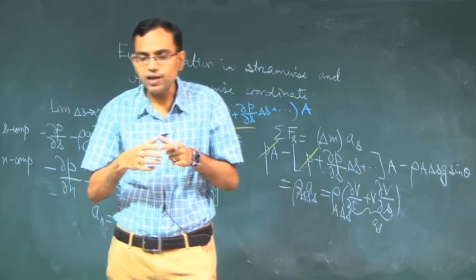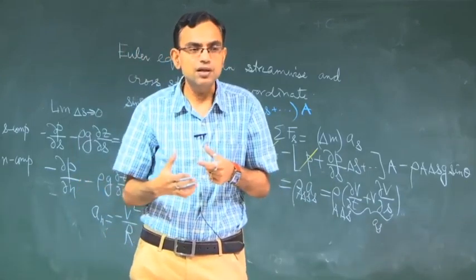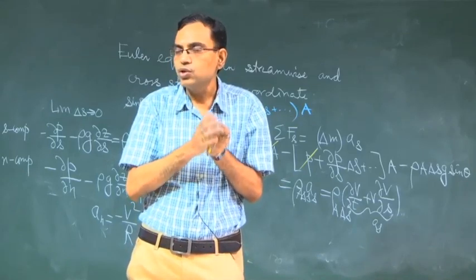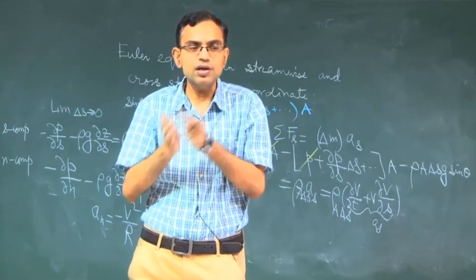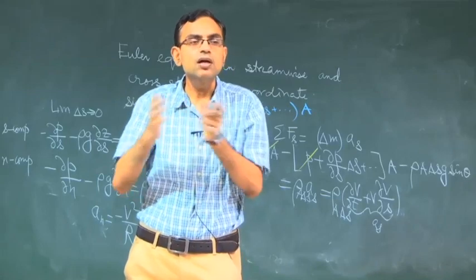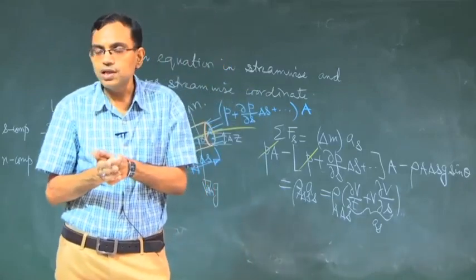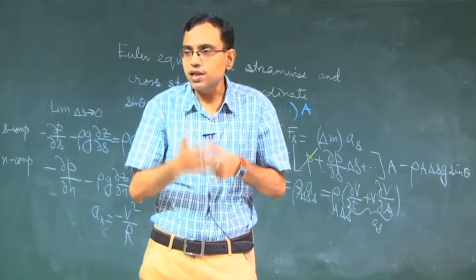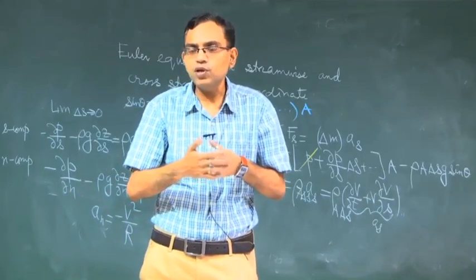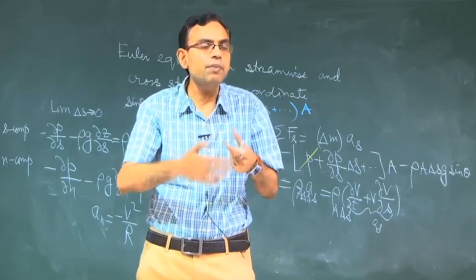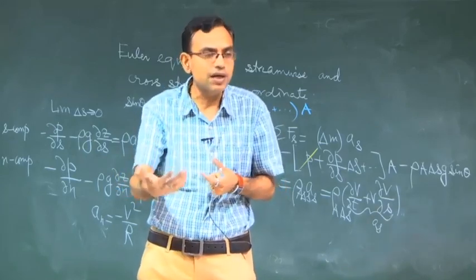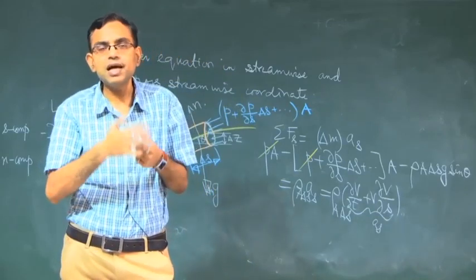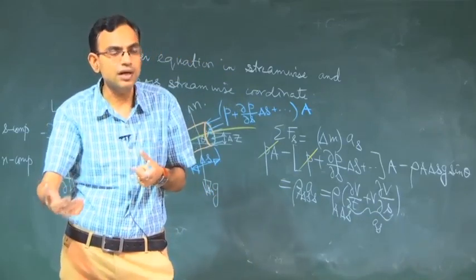So, a transformation is required that transfers the control mass based equation to a control volume based equation, or a systems approach to a control volume based approach. This is required more so because the systems approach is the approach on which traditional Newtonian mechanics has been established, but the control volume approach is the approach that we follow for fluid flow analysis.